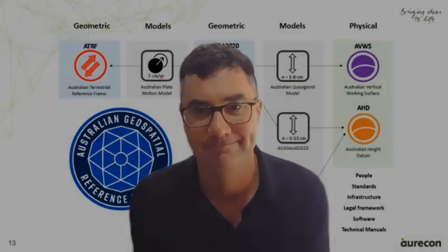That's GDA 2020. So, now that you are aware of the issue of scale factor, what should you do about it if this carrot or even pea-sized problem is too much to stomach? Well, there are two common ways to deal with it. The first, believe it or not, is to ignore it. If the scale distortion is small enough, it's not worth lying awake about at night. And for all intents and purposes, you can assume that your model scale is exactly the same as the real world, which in many cases cannot even be constructed to that accuracy.